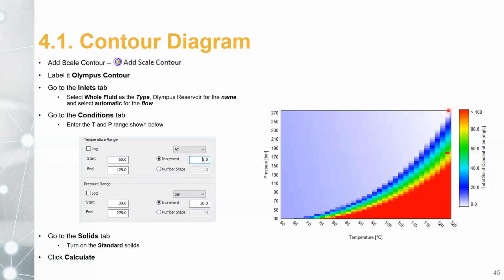What I have seen clients do with this plot is that they already have the pairs of temperatures and pressures, and they just plug them in here. Say you have the separator, so they know that they will have minimum or some scale formation. But let's say you are at 115 degrees C and 50 bar, then you are at the maximum scale formation at this condition.